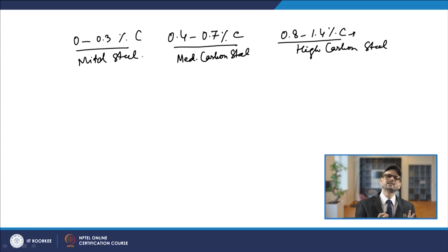Similarly, as we have already discussed, for the variety of cast iron, we use grey cast iron where we require the damping properties. So, for most machine beds we use grey cast iron, because in that case you have the cushioning effect which is given by the graphite, which is the soft phase.